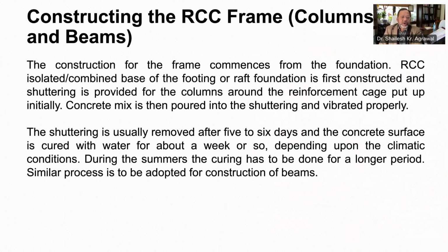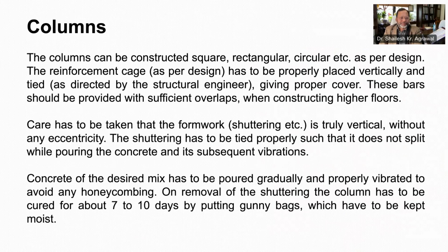Then concrete mix is poured in the shuttering and vibrated properly. The shuttering is usually removed after 5 to 6 days, and the concrete surface is cured with water for about a week or so, depending upon weather conditions. During summers, the curing may be done for longer period. Similar procedure is adopted for casting your beams as well.